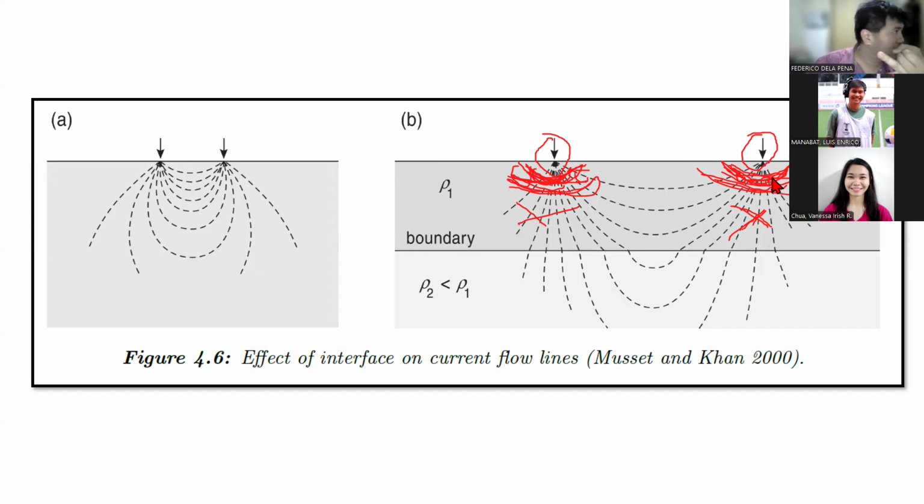So contact resistance arises when you have shallow insulating layers like rubber tires, a very dry desert, or a dump site that's full of plastic garbage. Or maybe a ground that's mostly just solid bedrock with minimal cracks and fissures, but that's very rare. Nevertheless, you can get contact resistance or almost zero penetration in these kinds of sites.